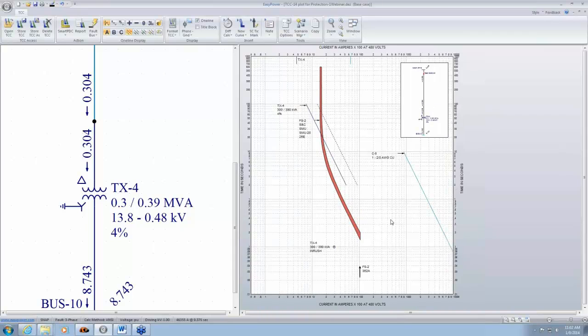So another point to look at is when you select fuses or any circuit breakers or any protective devices, we need to make sure that the inrush current is on the left side or below the tripping. If the trip device is faster than this inrush point here, then you'll get nuisance tripping upon energizing the transformer, and we need to avoid going into that nuisance trip condition. So in this case, the fuse is taking longer time to melt than the inrush time here. So I think it's doing a good job of protecting this transformer and allowing the inrush current to pass through as well.